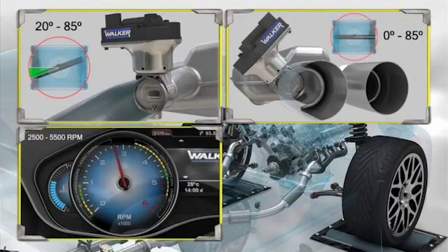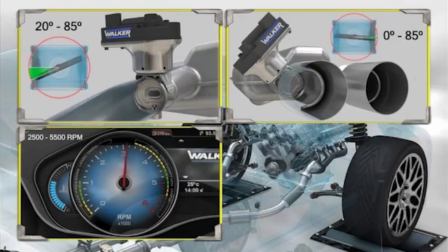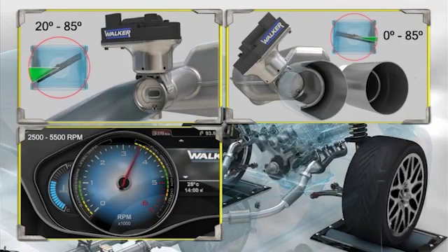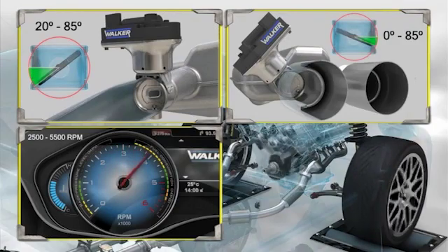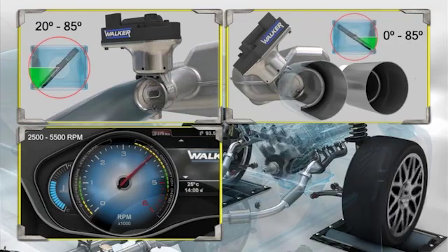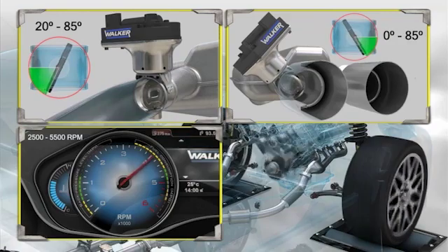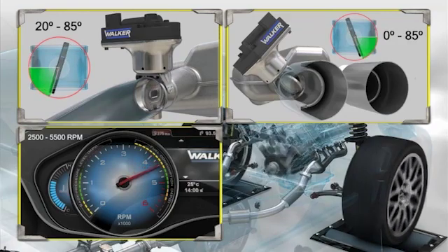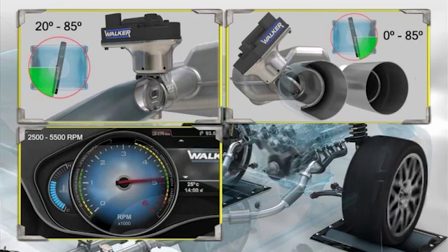From 2500 RPM and up to 5500 RPM, the valve begins to open progressively to compensate for the increased back pressure due to the increased amount of gases now flowing through the silencer. This causes the back pressure values to remain more stable during different engine speeds.